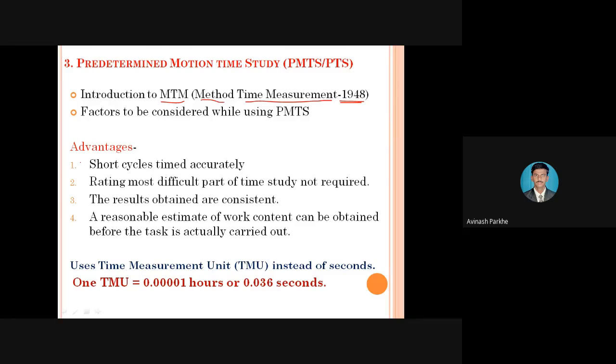So we have to complete that particular job in 2 hours. This is the rough value. Sometimes that job can be completed in 1 hour and 30 minutes, and sometimes in 2 hours and 30 minutes. But the rough value I have decided is 2 hours. Because in those 2 hours, sometimes tool breakage takes place, the oil or coolant runs out, and operators take rest, so extra 30 minutes are required.